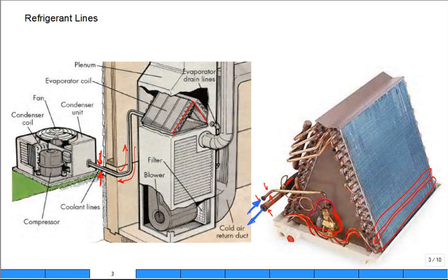So you can see these 180-degree elbows that redirect the flow back and forth in a serpentine path through the coil. And it's all finned on this side to promote heat transfer. It's sealed right in here, so airflow can't go there. It's forced to come and do a Z shape across the coil and come up. It's sealed up here, so the airflow can't. The air has to go through the coil.